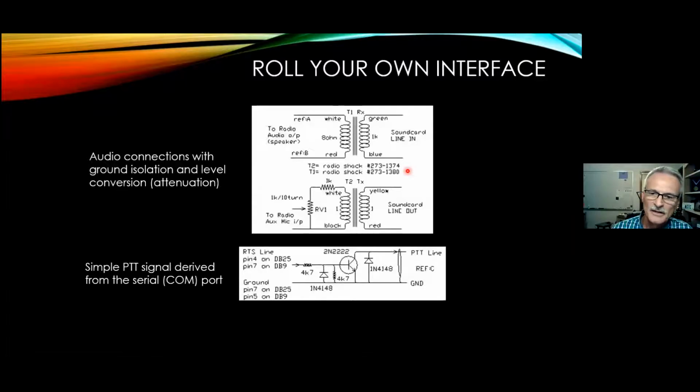Certainly, coming out of the sound card, the level is going to be a little bit too high to just drive a microphone circuit directly. You're going to have to attenuate that a little bit. And possibly the same thing going the other way, coming from the radio. If you're connecting to the speaker output of your radio, going into the sound card interface, again, you'll probably have to do maybe some impedance matching or maybe some attenuation there as well.